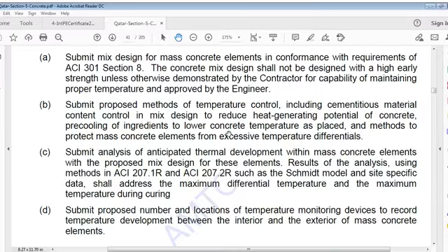It's very important to know that temperature applies on mixing, and it applies on laying, laying meaning pouring, and it applies during initial setting as well as during the hardening stage, during curing, and during every activity of concrete. It's very important to understand.